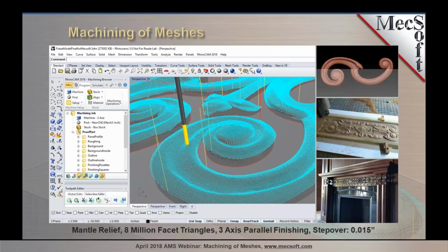I didn't spend a lot of time modeling. I didn't spend a lot of time tool pathing, because I knew I was going to be going through and completely hand carving the surface anyway. But even still, I got a really clean result. You can see in that middle picture on the right that this is just the first roughing tool path for the machining, but you can see that it produced, even at that, a very clean result. I refined it with one more tool path and then cleaned up the background, and it didn't leave a whole lot of hand carving left to do.